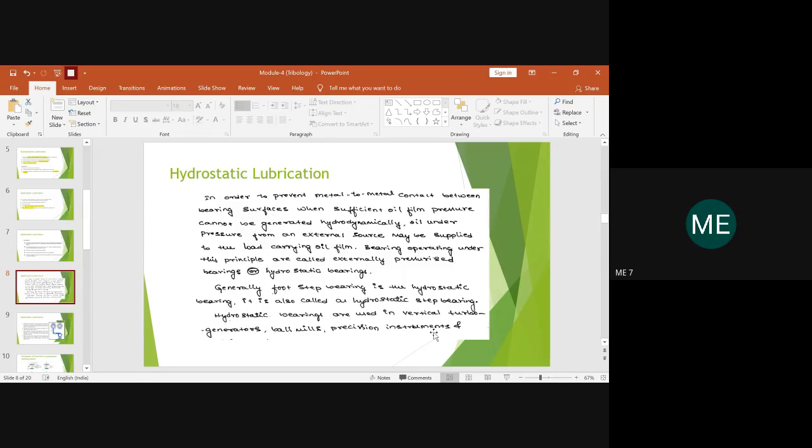So with respect to the requirement, you have to select whether to go with hydrostatic or hydrodynamic lubrication. Also, precision measuring instruments are very complicated and expensive equipment, operated to determine functional properties of smart materials as well, right? Here also the results should be very accurate. For that you cannot go with hydrodynamic, because there the shaft moves eccentrically and hence the positional accuracy is not so good. Where you need a measuring instrument with proper accuracy, it is always better to go with hydrostatic lubrication. These are the examples in which hydrostatic bearings are mainly used.